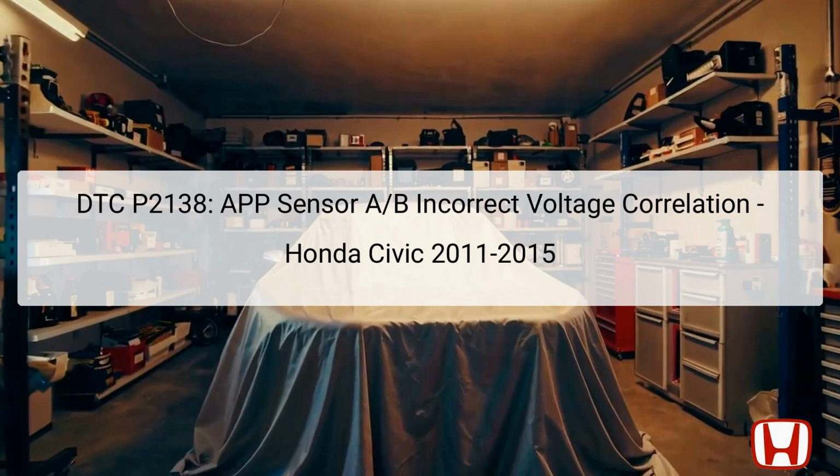The APP sensors are critical components located near the accelerator pedal, generating voltage signals that inform the engine control module, or ECM, of the current position of the pedal. These readings are essential for optimizing engine performance and ensuring smooth acceleration. When the ECM detects an incorrect voltage correlation between the two sensors, it triggers the P2138 error code, impairing the engine's performance and responsiveness. Understanding and addressing this DTC is important for maintaining vehicle functionality and ensuring safe driving conditions.